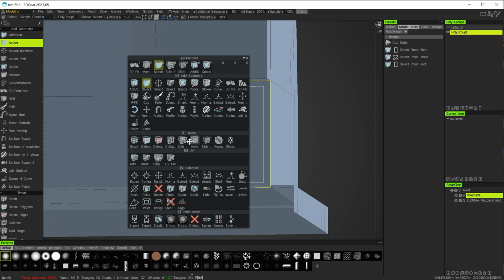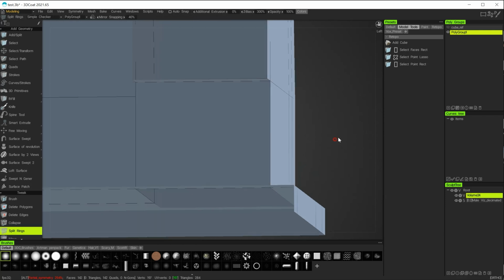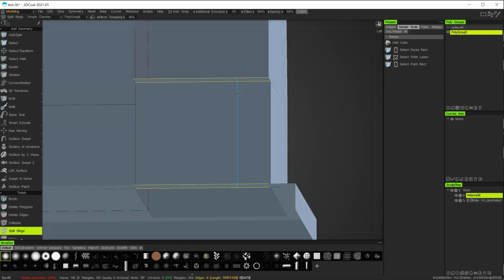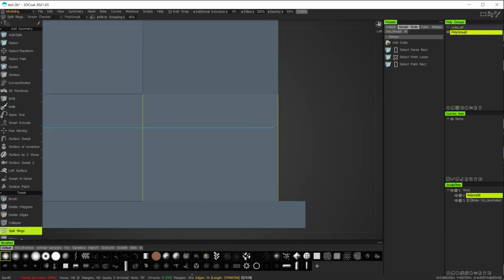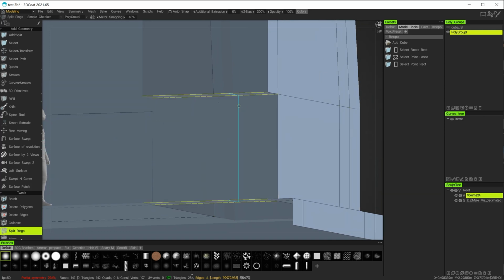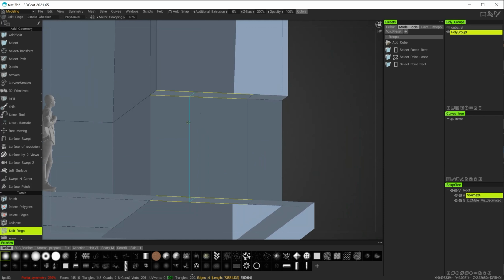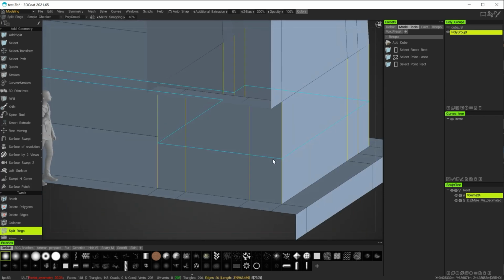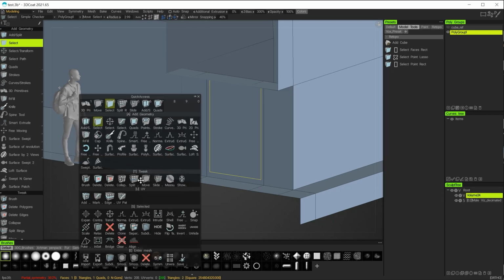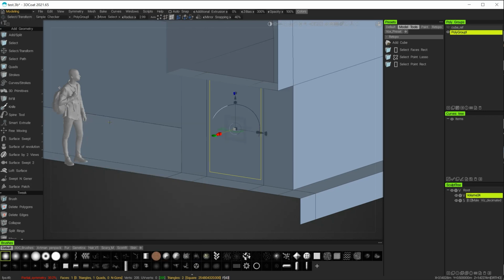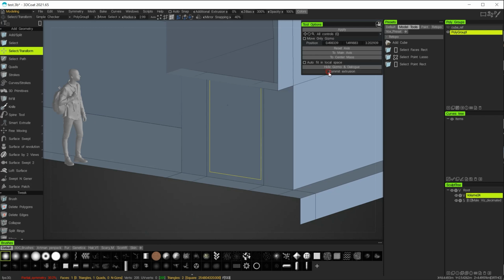which is the split rings, and it's a little bit easier for me to do it this way. So I won't use the grid or the snapping on this. I'll just sort of eyeball a kind of a rough passageway in here. So I'll put one there and one there, something like that. Then I'll select this tool, select that face, hit select transform, commit an extrusion.